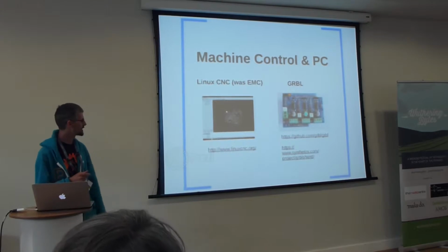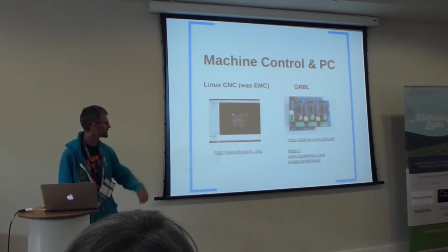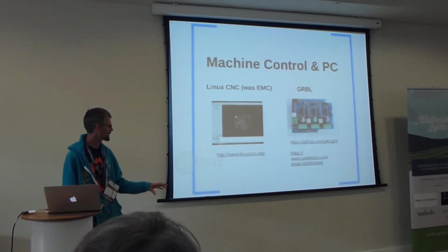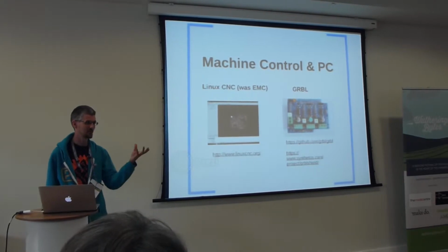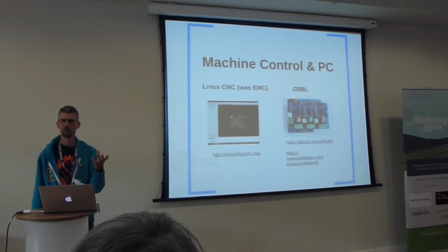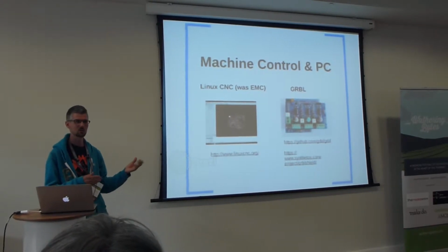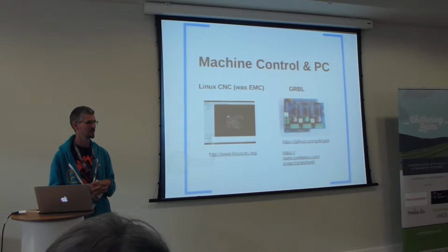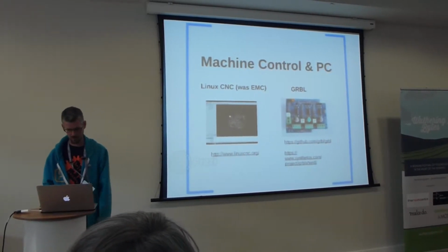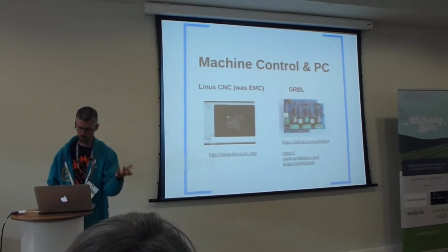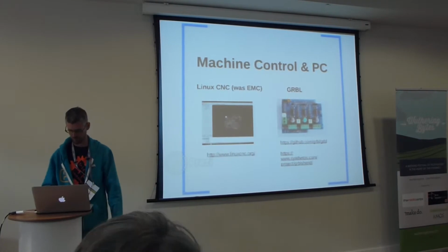One thing I also wanted to mention was this hardware version, GRBL, which is to run on the ATmega stuff like an Arduino, which has got stepper motor drivers. They've built some really cool firmware that makes use of all the timers, and then you get a real-time milling controller. So that's more like the 3D printer stuff, where everything is embedded on one control board. And you can buy a shield that will do all your motor control, if your mill is small enough. If you're doing something really big, you probably need much bigger stepper drivers.